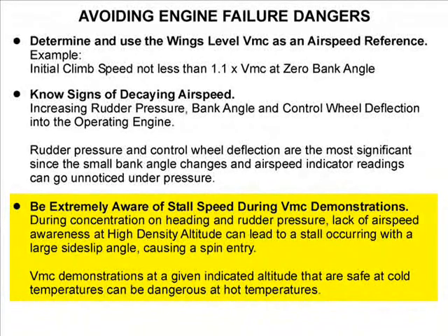During VMC demonstrations, it is extremely important to be aware of stall speed. While concentrating on heading and rudder pressure, lack of airspeed awareness at high density altitude can lead to a stall occurring with a large side slip angle, causing a spin entry. Remember that VMC demonstrations at a given indicated altitude that are safe at cold temperatures can be dangerous at hot temperatures.